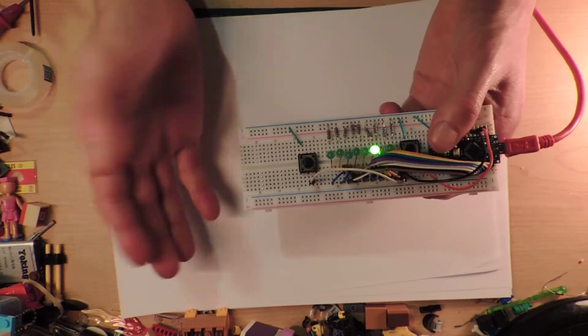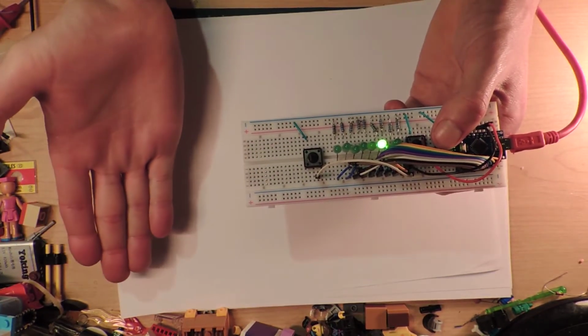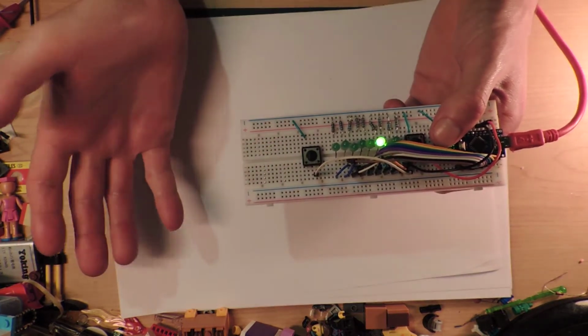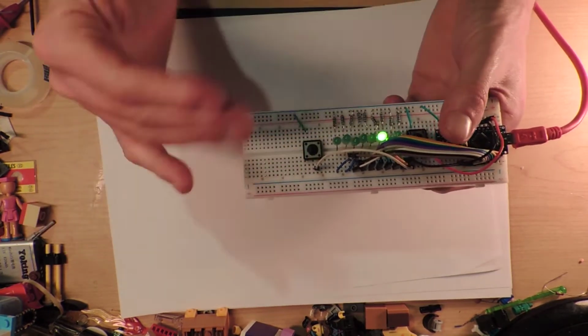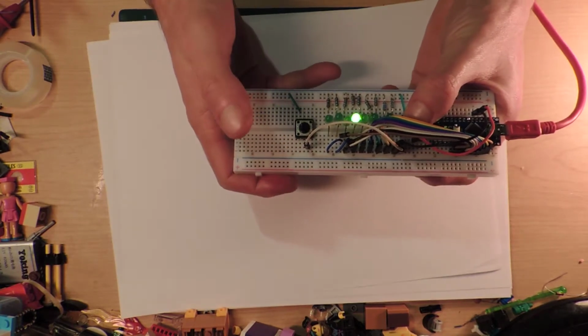So of course what you can do is check that the button was held down for at least a certain amount of time before going up again, or things like this. There are many ways of coping with this so that you can detect if it's a bouncing event, which is a very fast one, as opposed to an actual press.